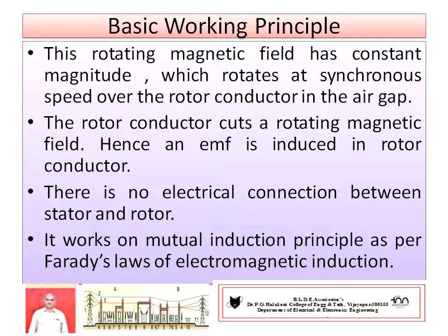Whenever a conductor cuts the magnetic flux or links a changing flux, an EMF is induced as per Faraday's laws of electromagnetic induction. Hence, an EMF is induced in the rotor conductor, and there is no electrical connection between stator and rotor. Electrically, both are separated. It works on mutual induction as per Faraday's laws.